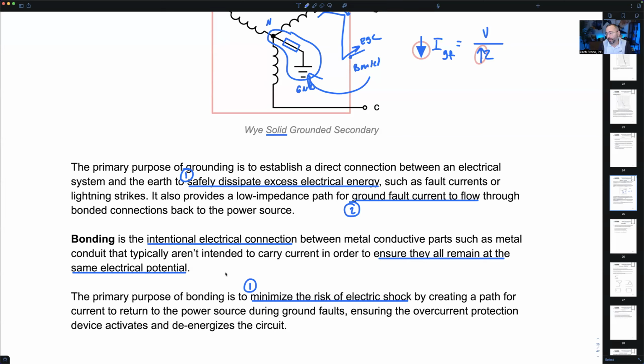So back to that maritime example, like Addison said, equipment on ships are bonded but ungrounded. Imagine all of your sensitive ship's navigation systems, its instrument panel, all that kind of stuff. If all of this equipment's not bonded, remember when current flows, it creates a magnetic field. And that magnetic field is going to induce voltage and current in anything metal nearby. No different than how transformers induce voltage and current from primary to secondary winding. No different from how induction motors induce voltage and current from the stator to the rotor.